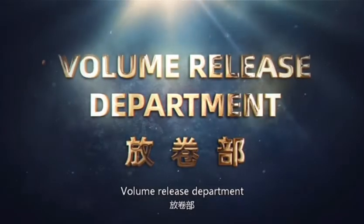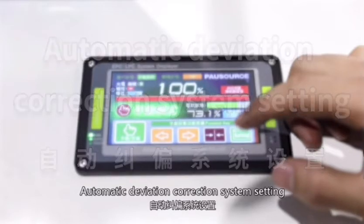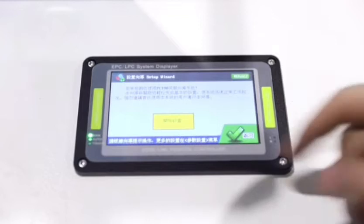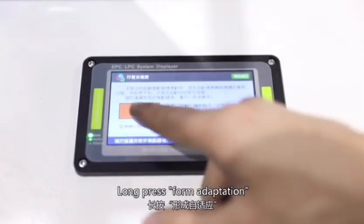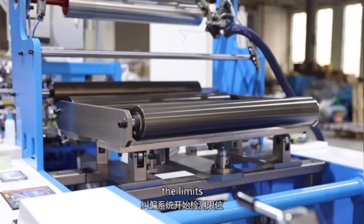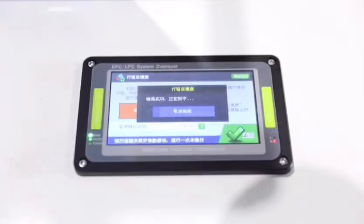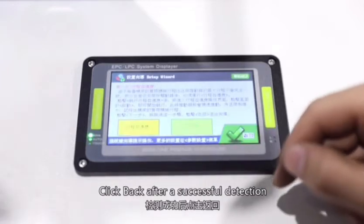Unwinding department. Automatic deviation correction system setting. Click Setup. Click Setup wizard. Click Start Setting Now. Long press phone adaptation. Click Start. The correction system begins to detect the limits. Click back after successful detection.